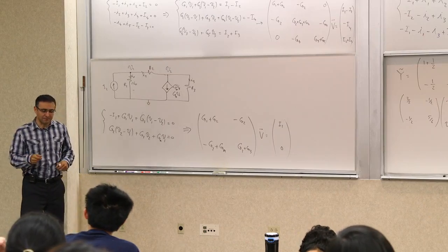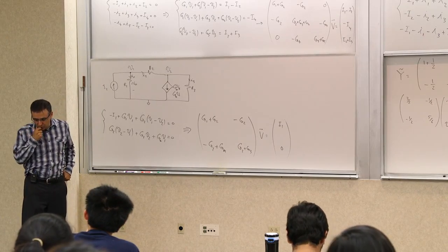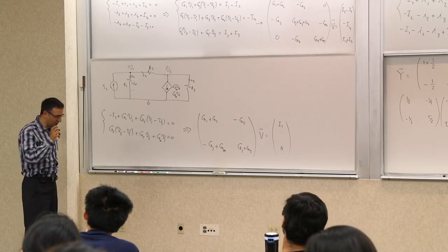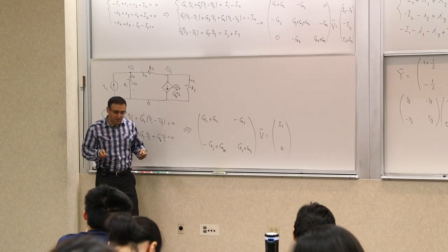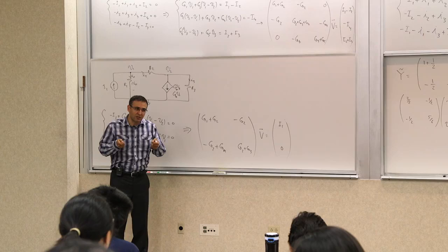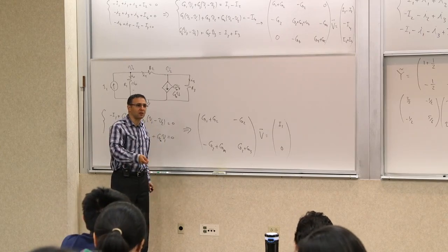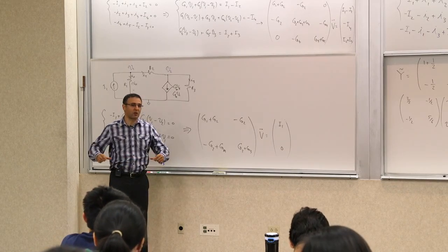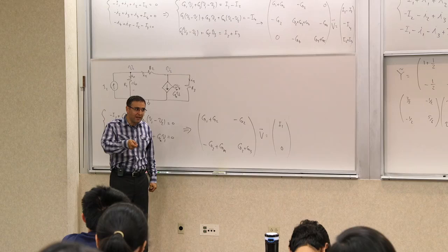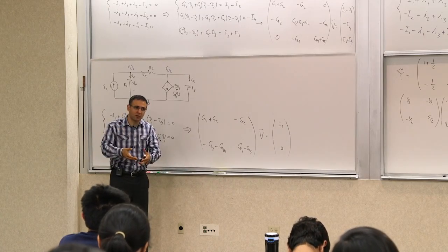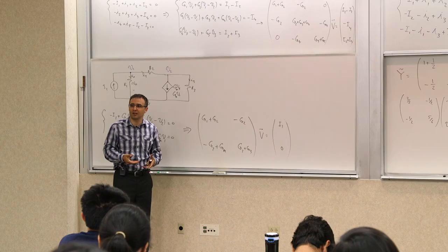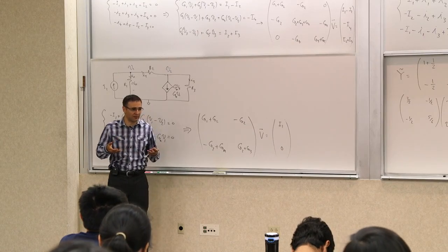One way to think about it, MOSFETs are probably easier to articulate in a couple of sentences. Think about a piece of semiconductor whose conductance is related to how many electrons are in a certain part of it, what we call the channel. If I apply electric field to it, I can get more or less electrons in that channel, or charge carriers.